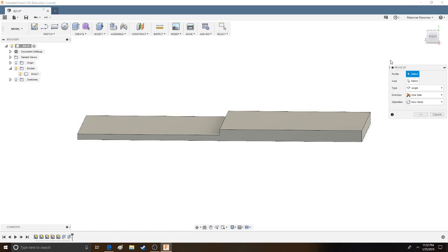So click on revolve, and it's kind of the same menu you get when you click on extrude, but instead we're going to have things like angle or to a certain point or full revolve or type, and of course multiple sides. By clicking on something like this, and then the axis that we're going to rotate over. That's pretty interesting going from extrude to selecting an axis, but don't worry, it's pretty easy. Any curve or edge counts as an axis.